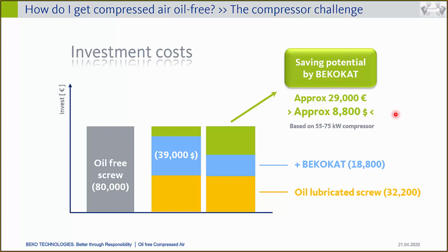In many cases, many companies start somehow with a regular application, with a production area where a regular compressed air quality is required, let's say the 242 quality class. And later on, they build up new premises where an application is integrated that requires an oil-free compressed air quality. So he can still leave the lubricated compressor there if it's big enough from the airflow. He can just add the BEKOSPLIT on site of the new premises and has a point of use treatment for his brand new application. That is also just an example to be considered.